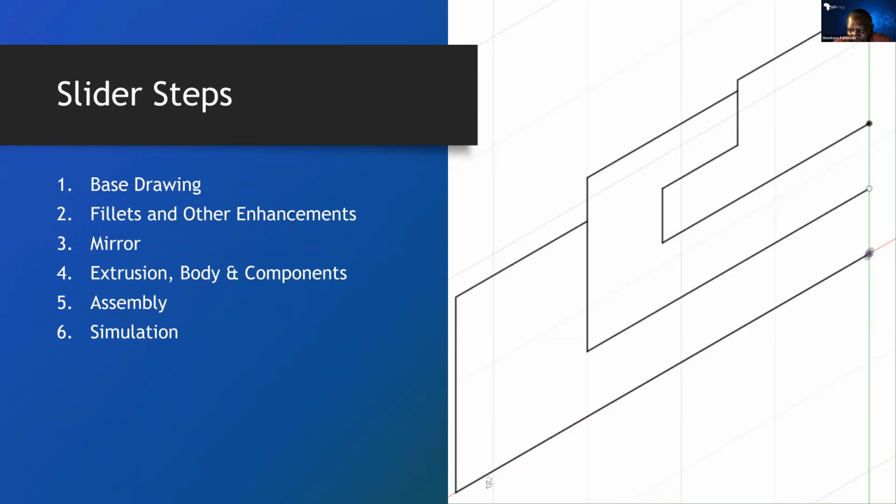We are going to make double lines instead of single lines, and you'll see the tools that we use to do that. And then we are going to create what will become the groove and some other things to make it do the work we want to do. After that, because we are drawing only half, we are going to use a mirror facility to produce the other half, but not until we are completely finished with one side.